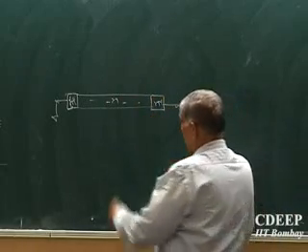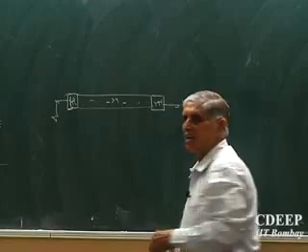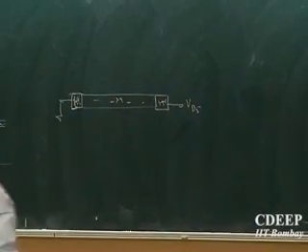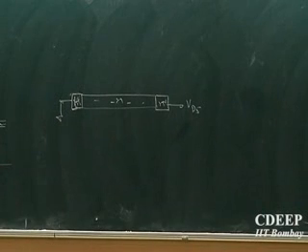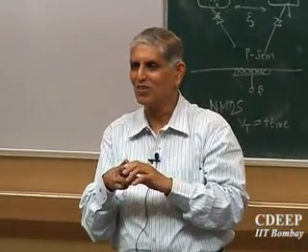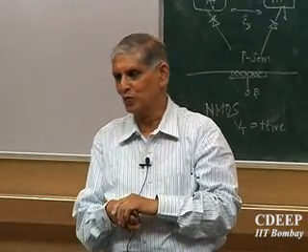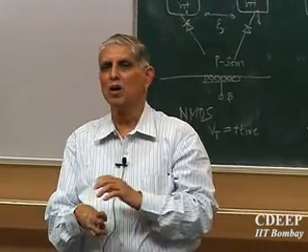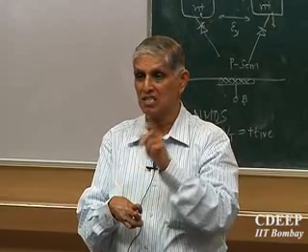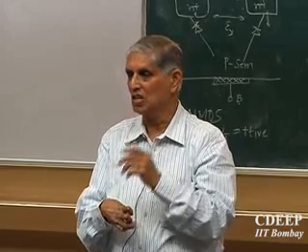Now I figure out that the current flowing in this is like a semiconductor bar. It's like a semiconductor bar. If sigma is the conductivity here, then I know J is equal to sigma E, the drift current will flow. If there is no gradient, then we say drift current will flow. That means the MOS current transport is essentially because of the majority carriers N, which is essentially the drift current.